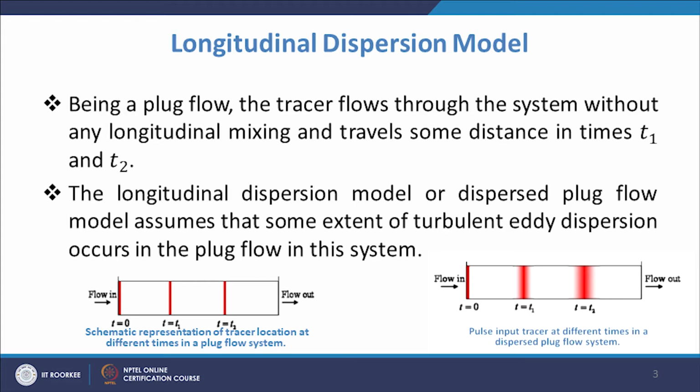However, when we talk about the actual case, you will have dispersion in the longitudinal direction. It is also known as dispersed plug flow. It assumes that there will be some extent of turbulent eddy dispersion occurring in the plug flow in this case.